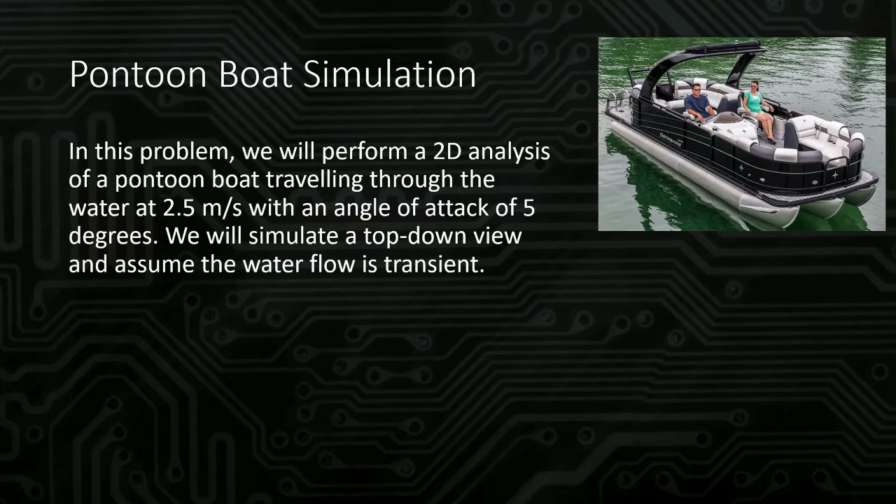So for our problem, we performed a 2D analysis of a pontoon boat with 3 pontoons traveling through the water at 2.5 meters per second with an angle of attack of 5 degrees. We simulated a top-down view and assumed that the water flow was transient.